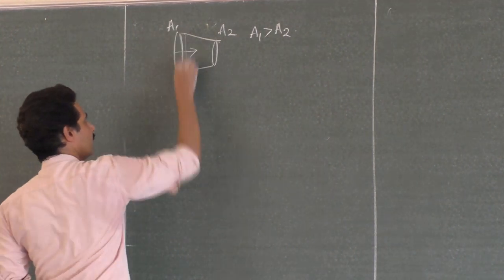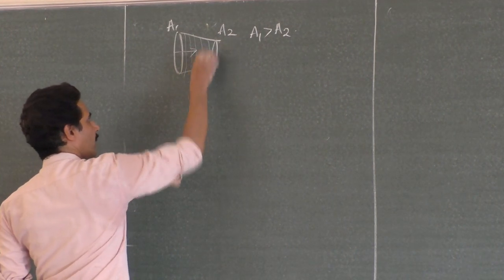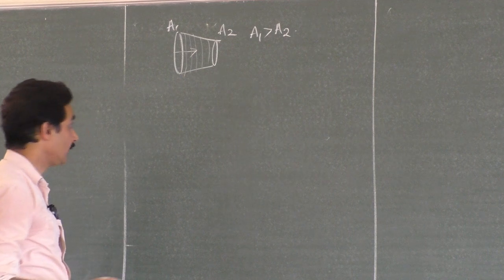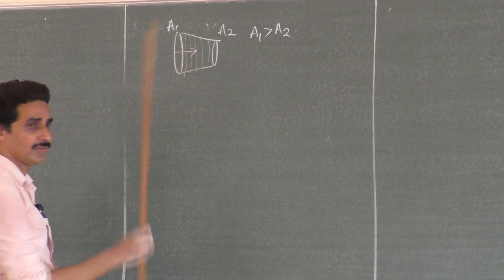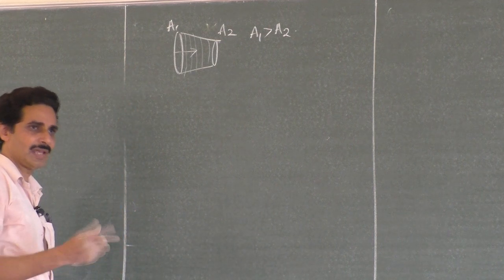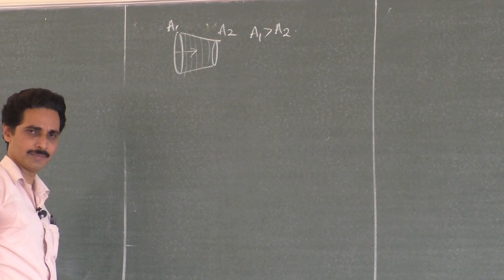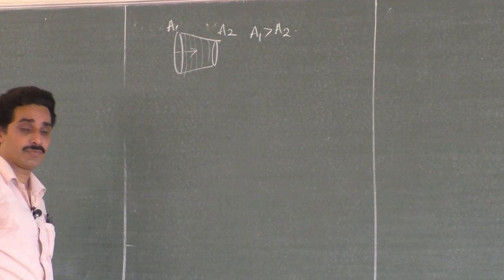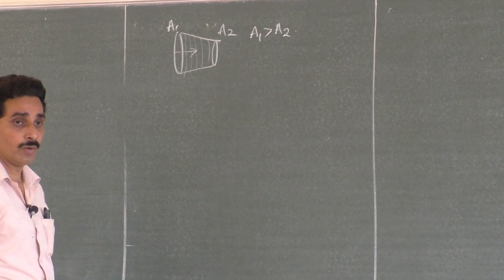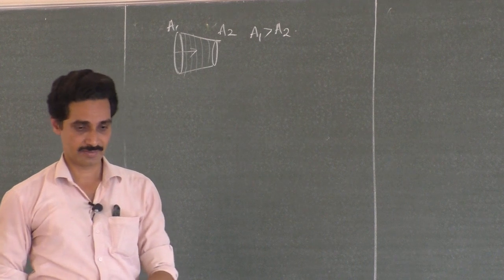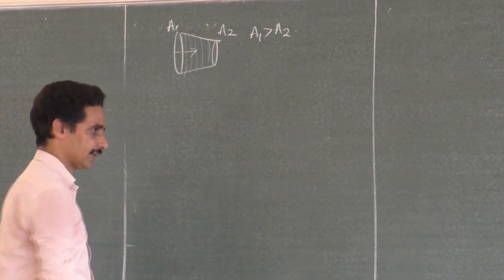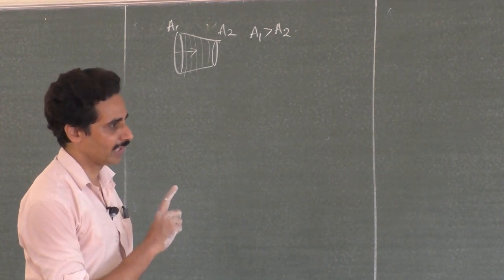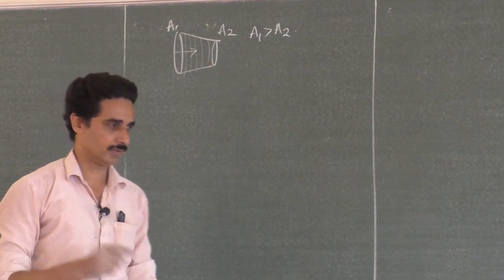You divide this into different parts like this. Will you get small coin-like arrangements? And will they have different resistances here, right? Resistance of this will be different, because their area of cross-sections keeps on changing. Now, is it not like different resistors in series? Whatever be the amount of resistance, when you connect them in series, definitely what is same? Definitely, current is same.